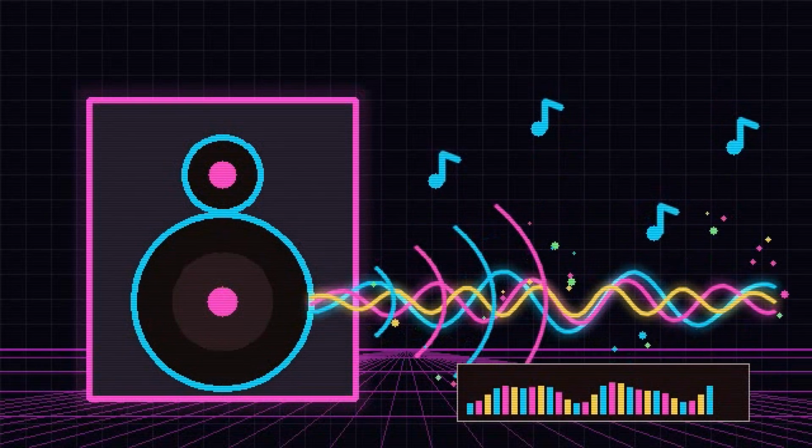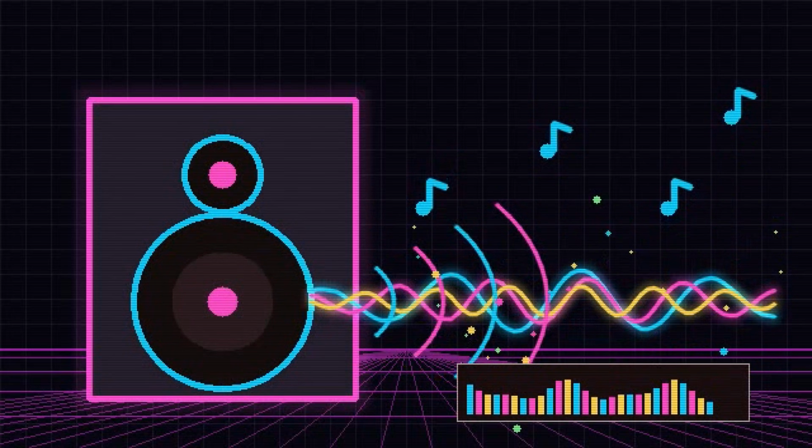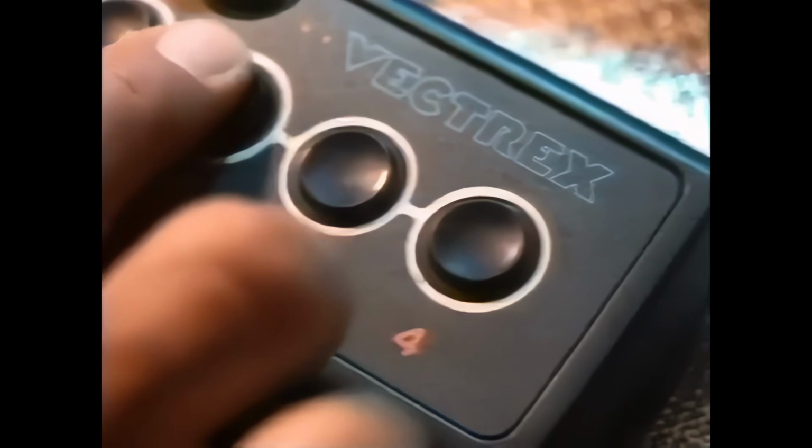The solution was slightly counterintuitive. I reduced the sample rate to 8 kHz. That meant the audio loop ran less frequently, giving the Spotify decoder more time to work. The buffer remained full, the clicking disappeared, and the playback became stable. Of course, 8-bit mono audio at 8 kHz is not exactly high fidelity. It sounded more like an old telephone or a vintage radio on an early computer, but on a Vectrex that feels strangely appropriate. The music remained clearly recognizable, playing through a speaker originally designed for arcade blips, lasers and explosions.